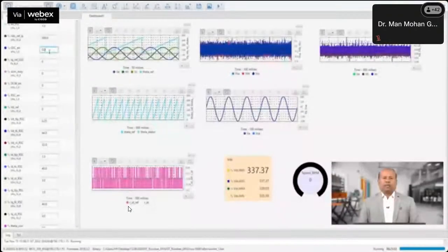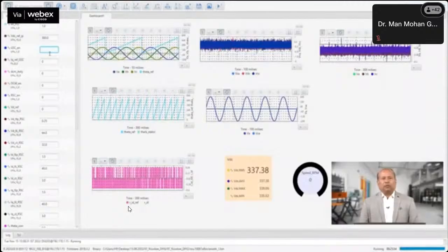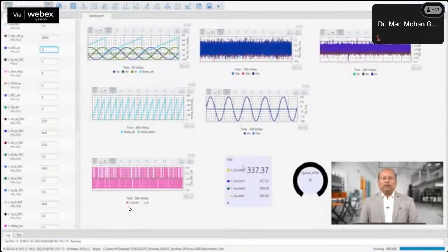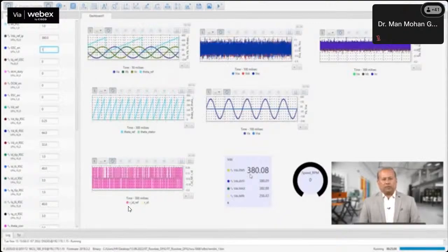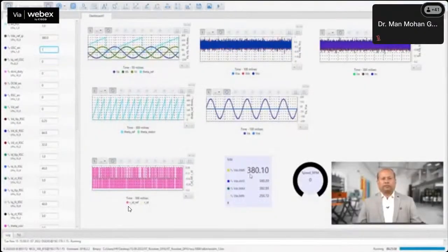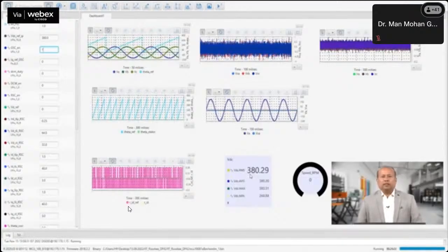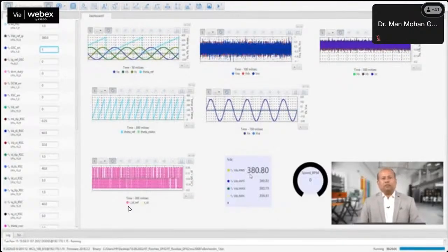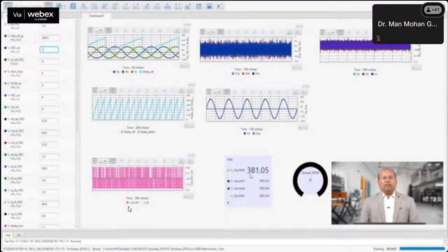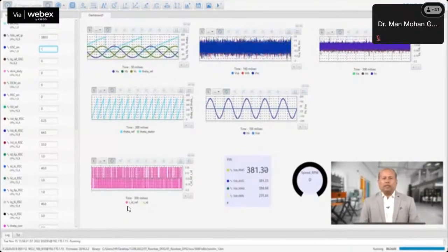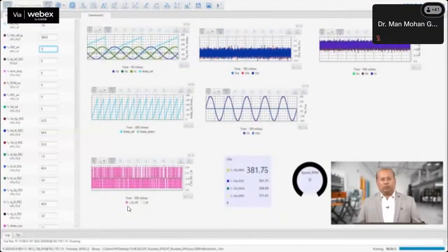Once the DC link is charged, we enable the GSC control to maintain the desired DC link voltage, which is set to say 30 volts greater than the DC link voltage, that is close to 380 volts. We see that the GSC tracked the DC reference voltage and the measured DC link voltage is read as 385 volts.